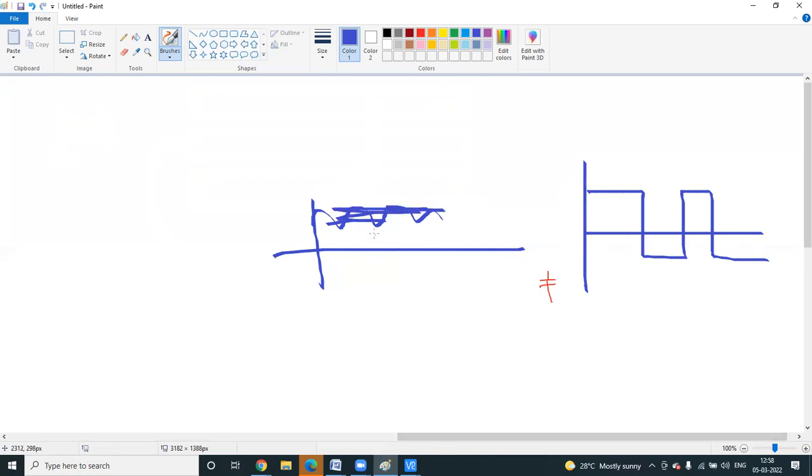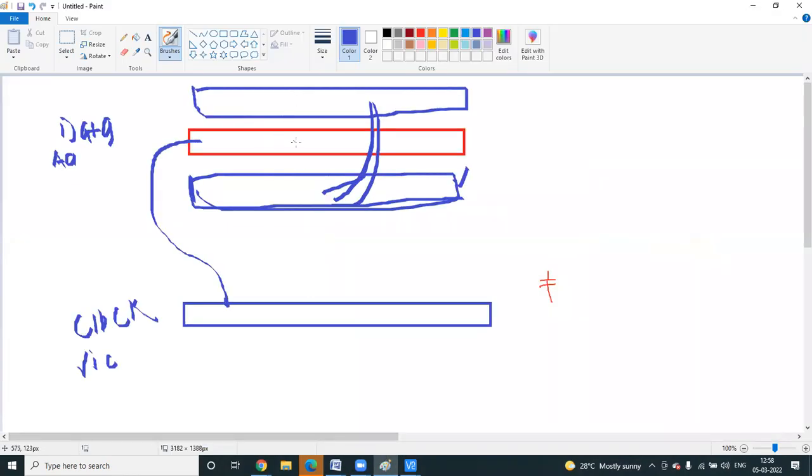So if you are protecting this by using shielding, this noise will not come. So how to protect this type of two type of shielding? Always remember, in an interview also, if one is a data signal and another is a clock signal, you have to shield the data signal first because that is the aggressor.